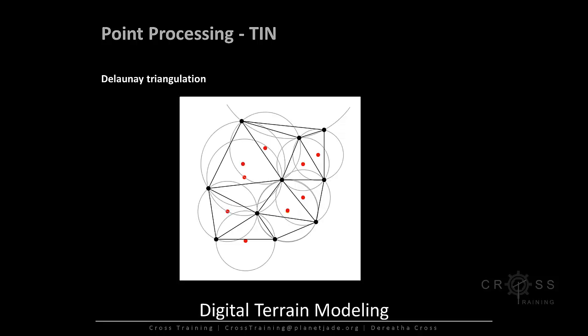So TINs are most commonly used to calculate volumes, especially between two surfaces, such as existing and proposed. So this is going to be pretty useful to us when we have to calculate earthwork, cut and fill.